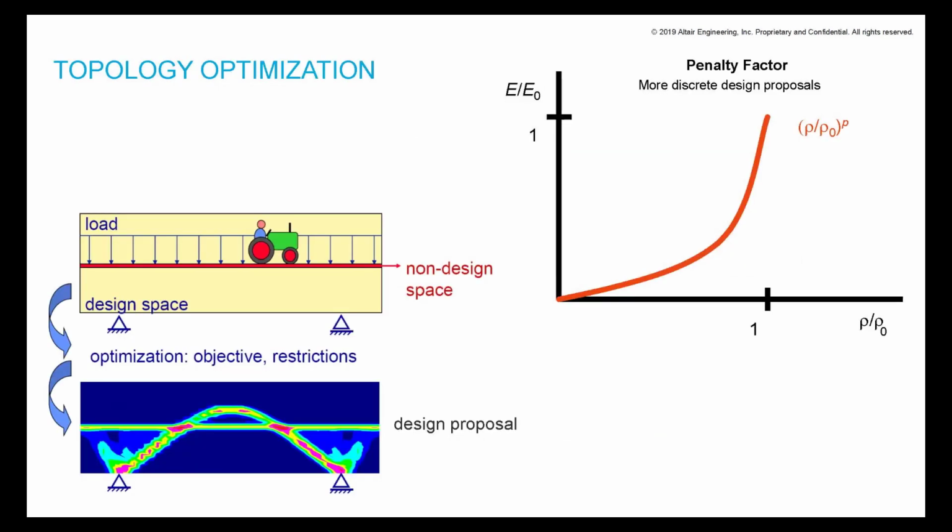Topology optimization problems are solved using the density method, known as the solid isotropic material with penalization method. The density of each element is varied continuously between 0 (void) and 1 (solid). Intermediate values of density represent fictitious material and are not meaningful.